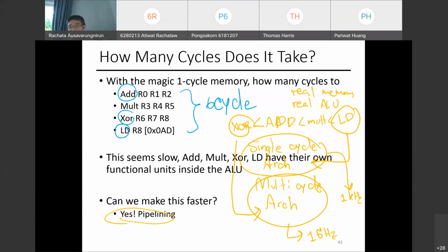And you can even clock faster. You can clock it super fast so that XOR takes 10 cycles, add takes 20 cycles, multiply takes 40 cycles, right? As long as you can make sure you can pick the value for the select line in time, you're good. So it doesn't matter anymore what instruction you have to support in terms of figuring out the speed of your clock. You decouple that. As long as you can select at the right time, that's it.